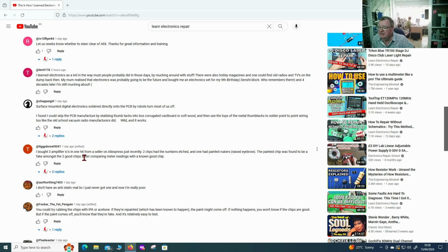We have a comment here from Tiggy Dorset. He's saying, check the markings on the chips, see if they've been painted on, for example. He gives me a case where he had a painted chip that was found to be fake with 2 good ones after comparing meter readings with a known good chip. I don't have any known good chips, but I did check on 3 of them and they all read the same. Okay. And similar, Fubar the Fat Penguin.